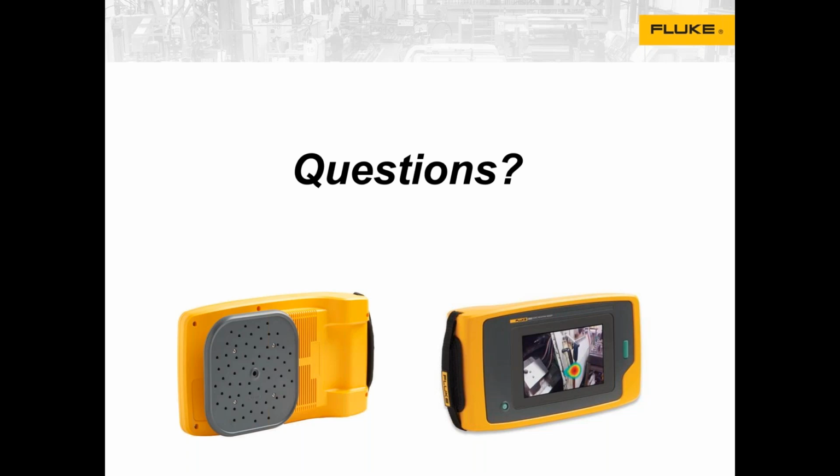Yes, indeed. First question, what is the Fluke suggested or recommended frequency range for identifying compressed gas leaks? Justin, you want to take that? I typically set it between 18 and 24 kilohertz to start, and then I scan up if there's ambient noise. But I'll let Justin share his expertise there.